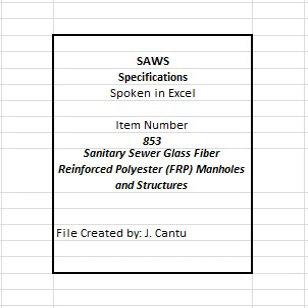C. Contractor is hereby instructed to conduct either of the 2 identified tests in the following manner. D. Hydrostatic testing. Hydrostatic testing shall be conducted by utilizing approved plugs to seal all influent and effluent pipes in the structure and filling the structure to the top of the structure with water. 1. Additional water may be added over a 24-hour period to compensate for absorption and evaporation losses. 2. At the conclusion of the 24-hour saturation period, the structure shall be filled to the top of the structure